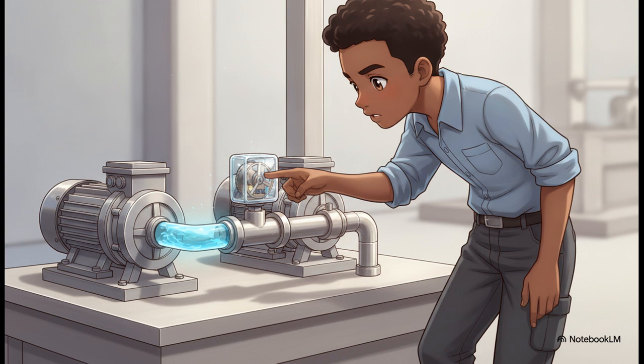Because of that, your motor power is incredibly low. We're talking 0.5 horsepower or even less. You'll set up 2 of these pumps, one running and one on standby just in case, and to keep track of everything, you slap a single digital or mechanical flow meter on the inlet or outlet to track your volume precisely.